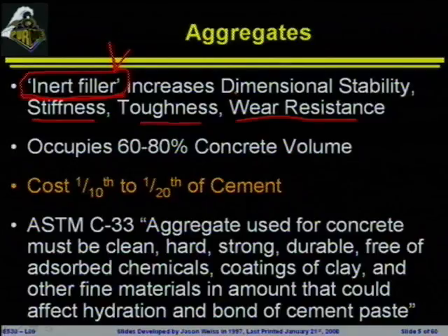They'll also provide the wear resistance, the resistance to things like studded snow tires, or the resistance to polishing when traffic goes across them, or in the state that I grew up in, the resistance to horses traveling across the concrete. And believe it or not, the horses in Amish country do a number on asphalt and concrete pavements. So each year there are research projects in Pennsylvania that are dedicated to horse interaction and trailer interaction with pavements because this is an important problem dictated by the aggregates that are in the overall system.